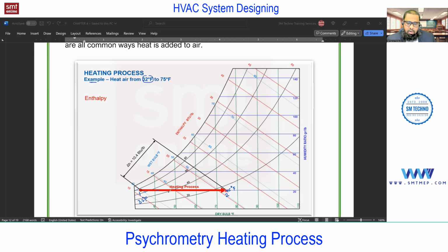So you can see on the psychrometric chart, going along the state path from left to right is what? We already discussed this in the previous session. It is the temperature increase. You see this scale increases horizontally, and in the vertical orientation you'll find the lines, but the increase in horizontal is the increase in dry bulb. So you see an increase in dry bulb, but what about the other conditions?